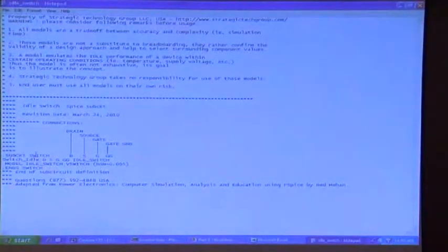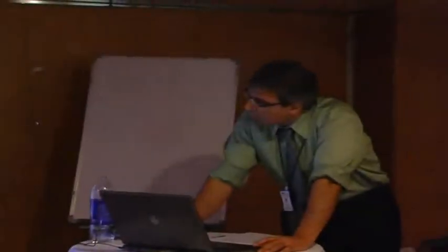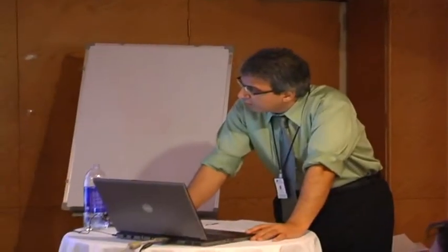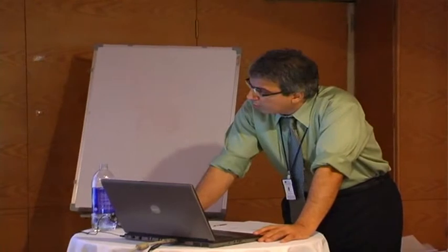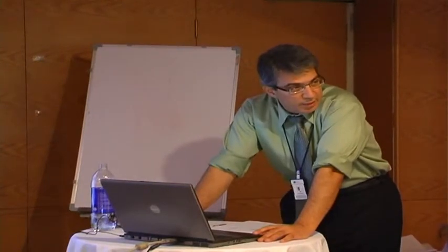Okay. Now, if you want to simulate, this is a text file. Basically, you have a subcircuit called switch. It has got drain, source, gate, and gate ground. So it's got 4 terminals. And the model we use is ideal switch, where we have set R on to be 0.005. So we control R on to be 5 milliohms. And you can change that parameter as you like.